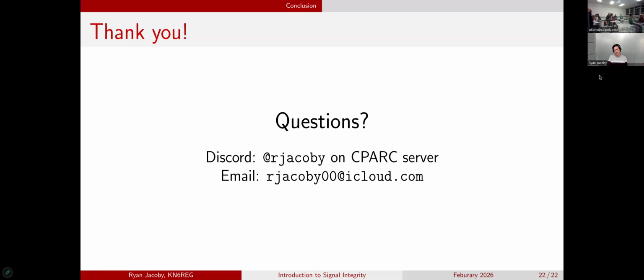I think that's a 10 or 100 nanofarad capacitor on each voltage supply pin plus a 1 microfarad or a 10 microfarad on the whole package, something like that. It'll usually be on the order of 10 microfarads, 1 microfarad, or maybe 0.1 or 100 nanofarads per pin on a multi-pin device.